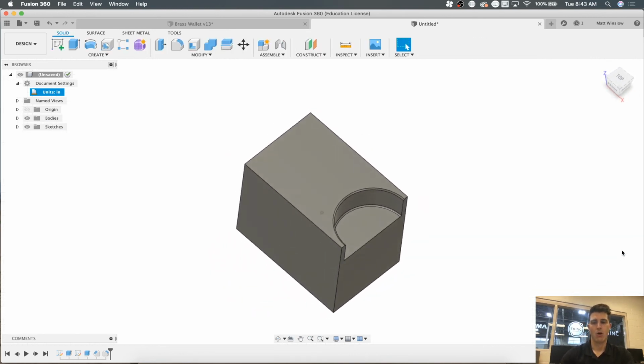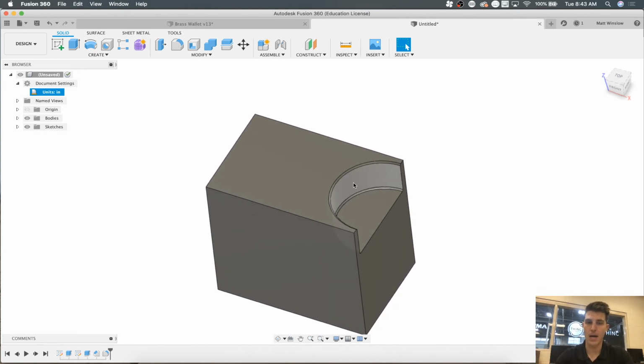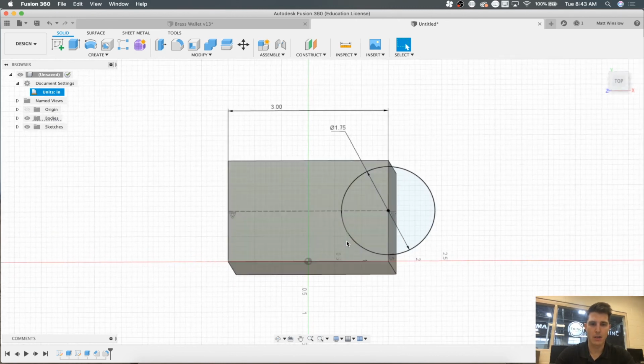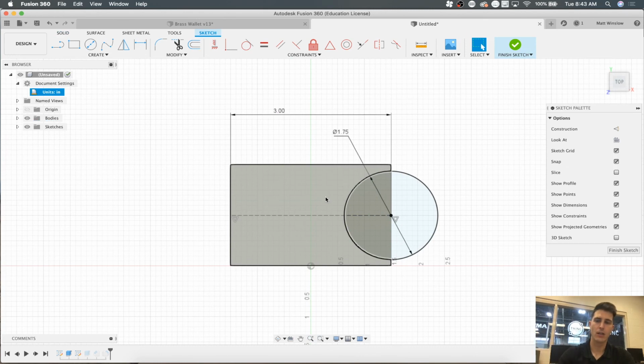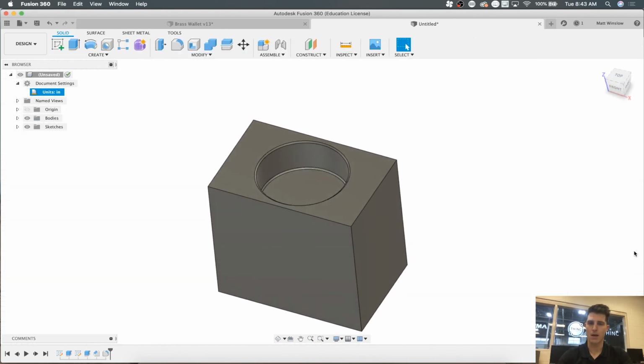Okay, so there can be implications, based on what you change clear back in the feature tree. So it is important to constrain things. Remember when I was talking about your sketch will go fully black? That means that sketch can't be moved, because then it's easy to go back into the profile sketch and go, well, I changed my initial size of that block, so now I'm going to move it right in the middle, 1.5 inches, and voila, we're set.